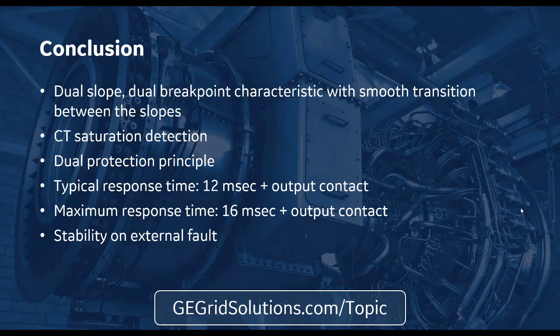But with a bus differential, if you have the CTs on the feeder side, then it can also incorporate the breaker as part of its protection scheme, and it will trip for any type of event that an arc flash relay would trip for. So again, it all depends where you have the CTs, but for all intents and purposes, they are kind of doing the same thing in terms of arc flash. They are going to reduce the arc flash energy. So if you have an arc flash relay, you are going to trip the bus for an arc flash event. If you have a bus relay, you are going to trip the bus for an arc flash event.